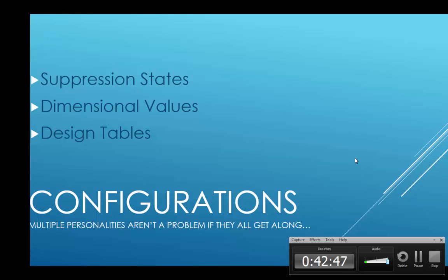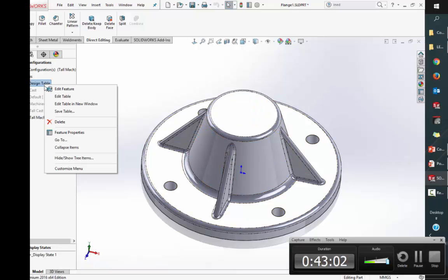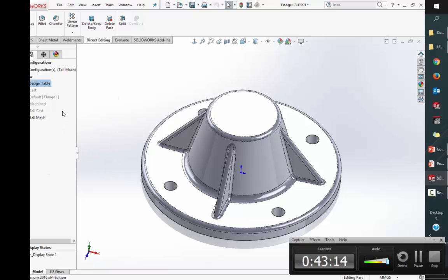Yeah, if you right-click on the design table in SolidWorks, it'll have an option to save it. It does, right? And I apologize. That saves an Excel file. Yeah. And in fact, if I take a look at it, that's a great point. It was fortunate I restarted it. Yeah, that's right there. Right-click, save table. So yeah, there you go. I forgot you don't have to do the copy-paste. See what you remember after 20 years, right?